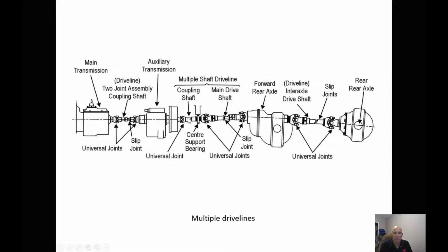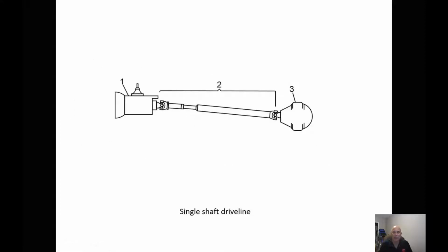So a few things that we want to take a look at. Let's first off take a look at just a single drive shaft. One of the things with a single drive shaft is we have to look at making sure the drive shaft is strong enough so that it can withstand the torque of the engine, transmission, and into the differential. We can't have a single drive shaft too long, or the drive shaft will start to whip as the speed increases.